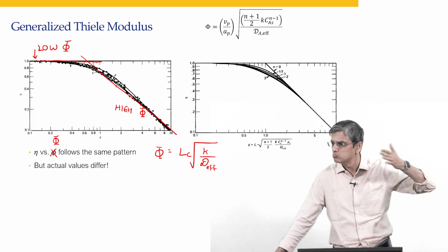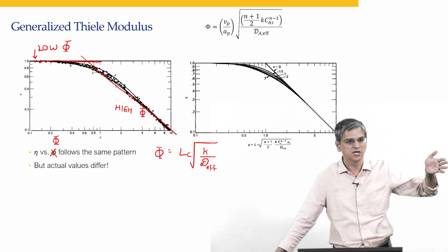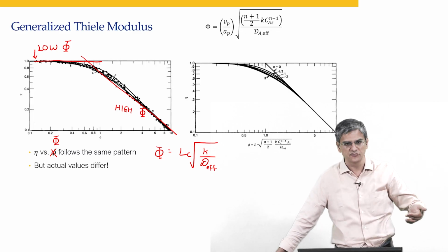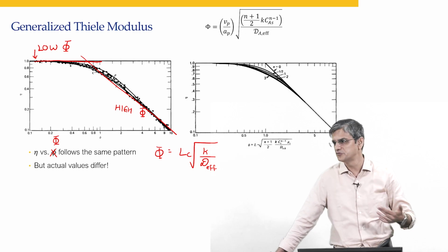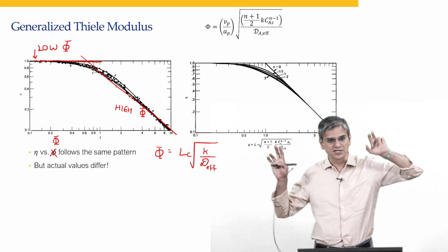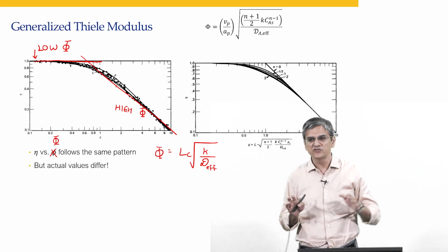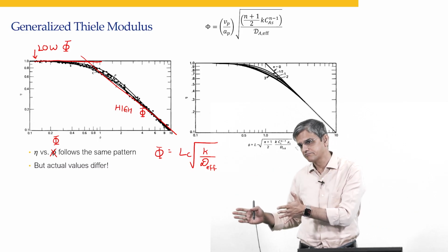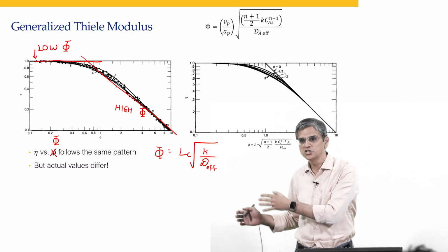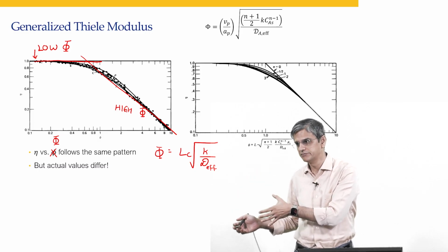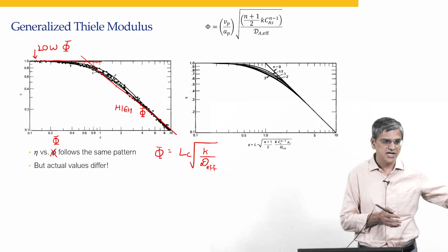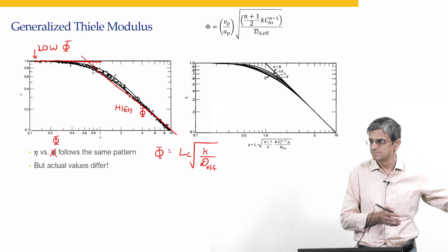When it comes to dimensionless numbers, similar things are valid, especially when it comes to the ratio of reaction and diffusion or the ratio of internal to external diffusion. So, the Thiele number that I talked about, if the Thiele number is greater than 10, diffusion is rate limiting. If the Thiele number is less than 0.1, reaction is rate limiting.